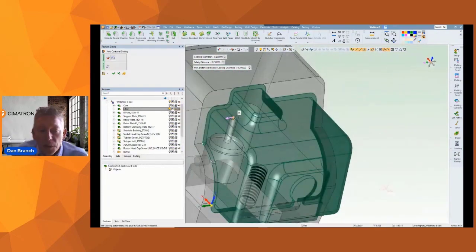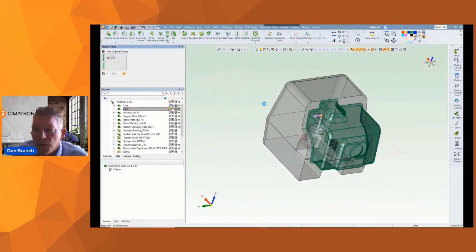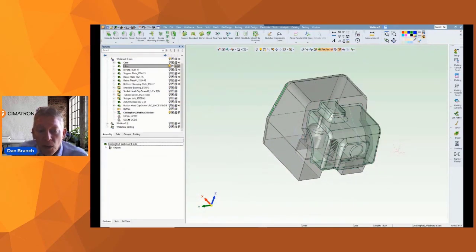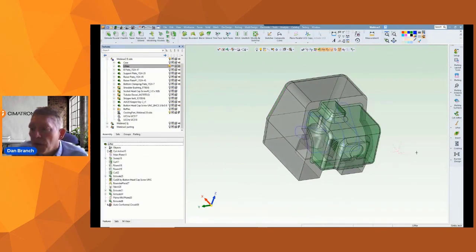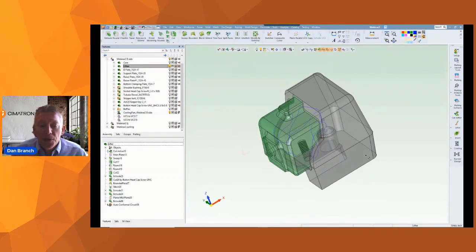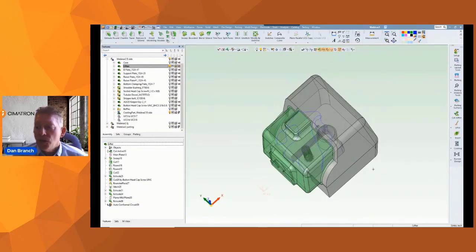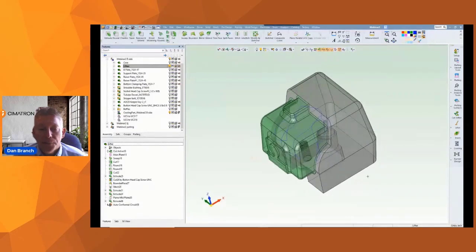Now, selecting where the cooling channel starts and ends isn't a required step, but in this case with the lifter, I know where the water is coming up from. So those are inputs I want to provide as well here. Based on those parameters, I've been given a blue curve, and that is the path that I could then choose in conformal cooling to lay a channel on.